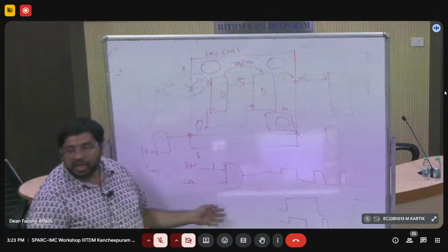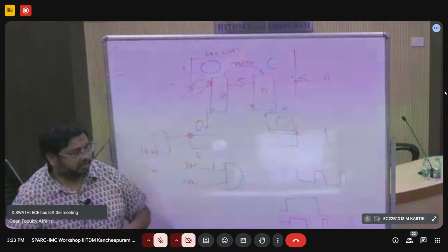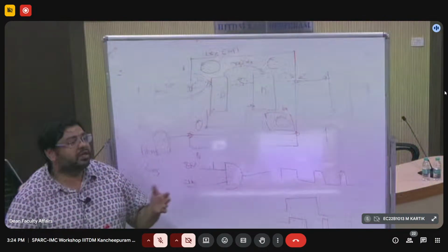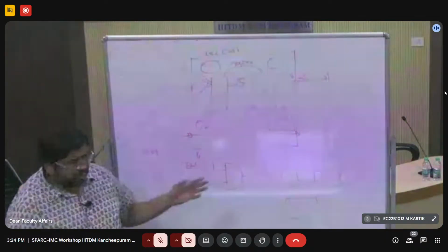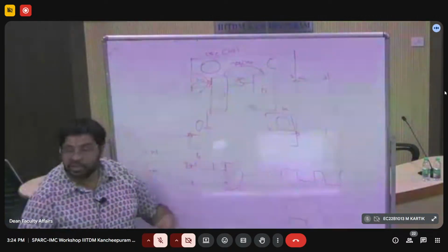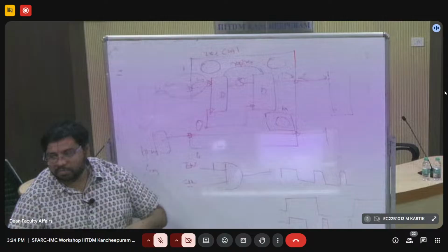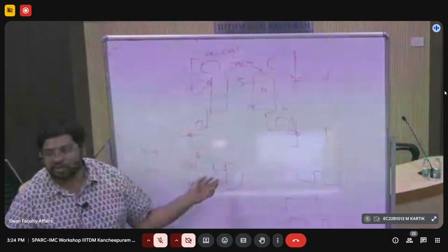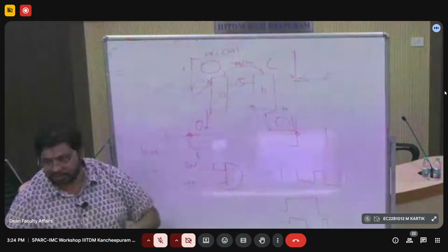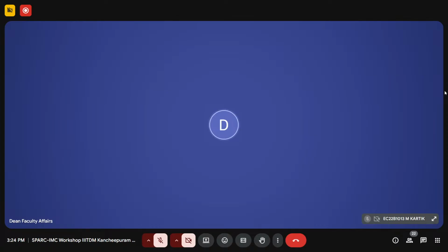So they have another proposal called latch based clock gating, right? When you use an AND gate along with an inverted latch, you will never have these glitch issues. I'll leave it to you to study that. You can come back to me with any questions tomorrow. Study the integrated latch and the normal gate. What is the difference? What are the advantages and disadvantages? So that is about low power. Now I'll get to the circuit.